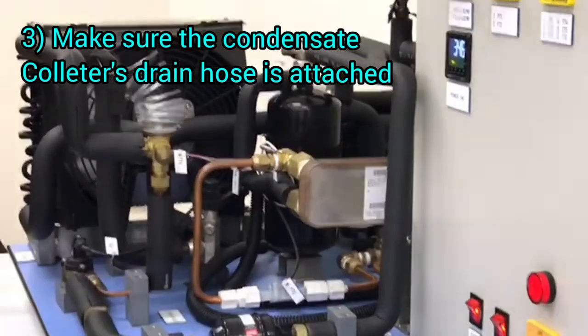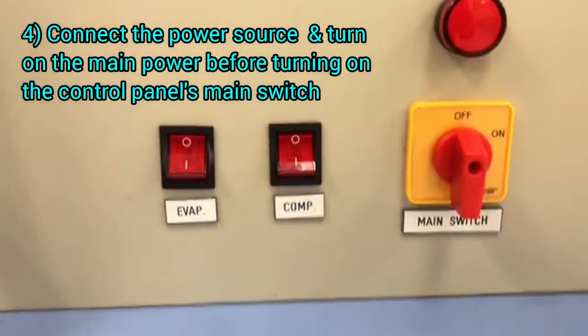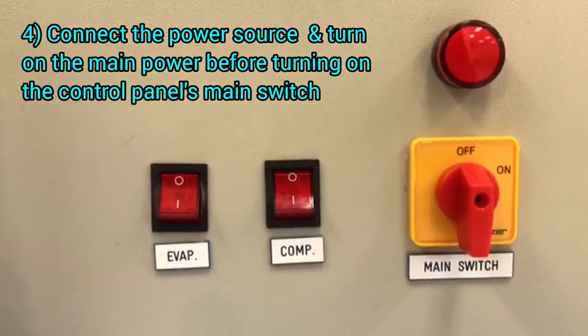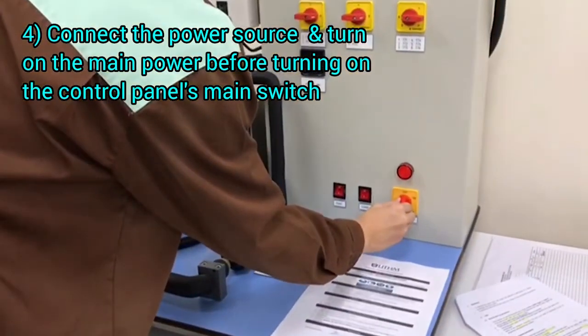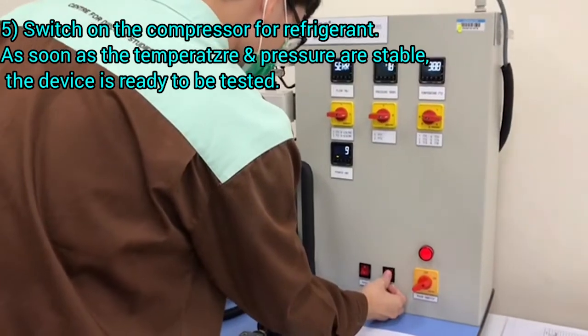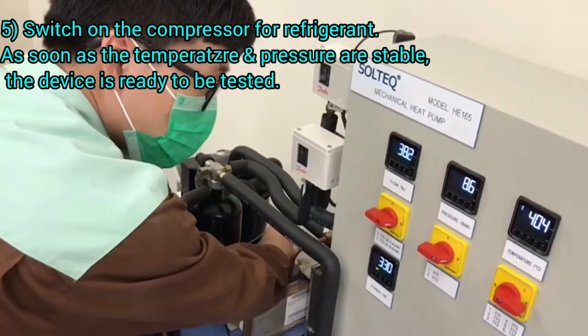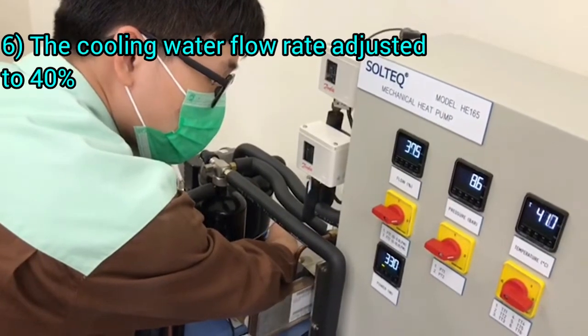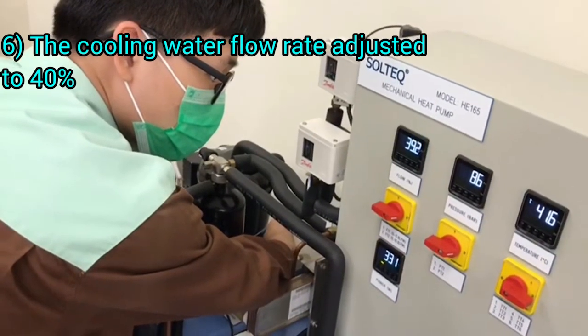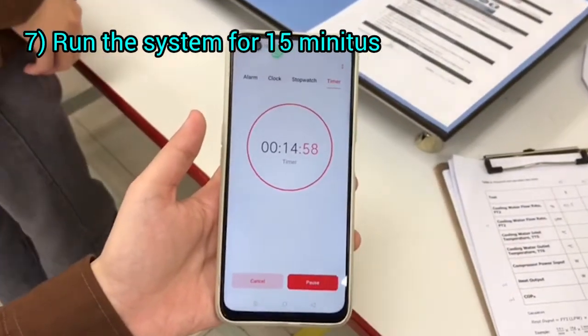Make sure the condensate collector's drain hose is attached. Connect the power source and turn on the main power before turning on the control panel's main phase. After that, switch on the compressor for the refrigerant. As soon as the temperature and pressure are stable, the device is ready to be tested. Next, the cooling water flow rate is adjusted to 40%. Next, run the system for 15 minutes.